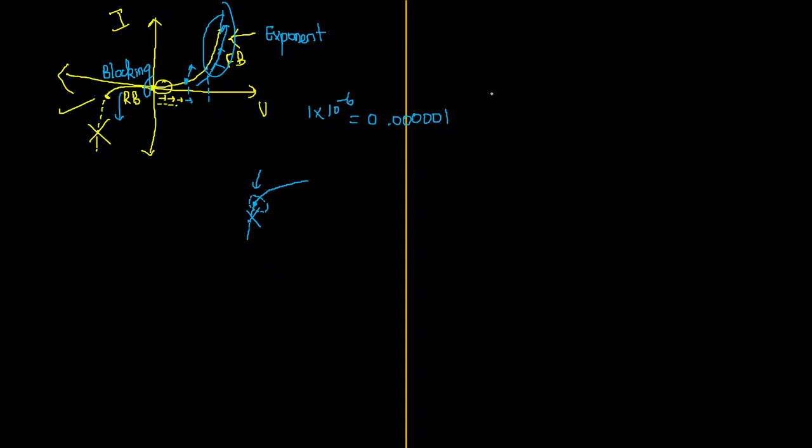0.0000001 ampere. So this value is approximately equal to 0 ampere only. So we are not considering this effect. This is not a significant value. So current is 0. Current is 0 means, according to our basics, that is an open circuit. Yes or no? So reverse bias is basically acting as an open circuit here.